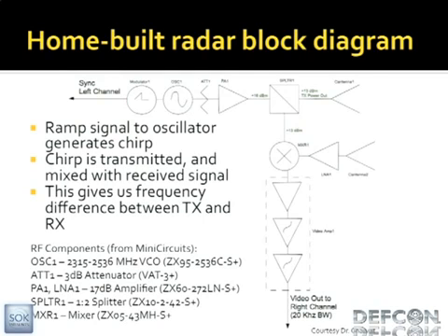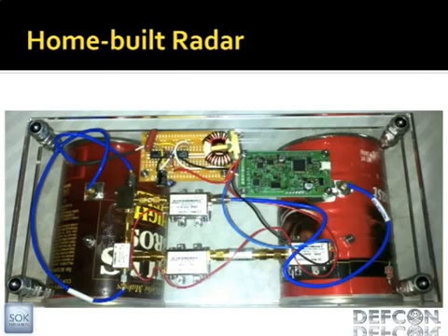But these are all off-the-shelf parts from this company called Mini Circuits, which builds these things. They take a little chip and put it in the package and do all the testing to make it actually work, and then you just screw on little SMA connectors to it. It's pretty cool because it's like doing plumbing, but you're building an RF circuit. So here's a picture of the thing that's sitting right there. I think I have call-outs on the next page.